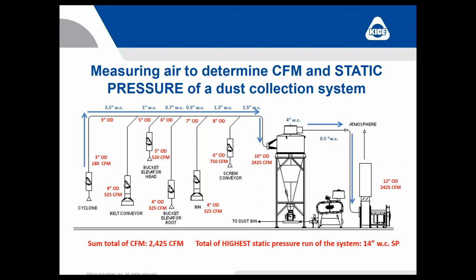So if you ask anyone to size a system and you said, I am looking for a dust collection system that can do 2,425 CFM, and I calculate that we need 14 inches static pressure, that's going to give them a very good start on what you need.